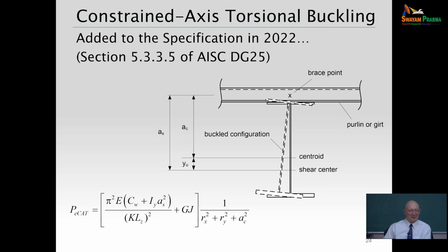But they don't go to the top flange. I've seen these details. They just go from the bottom web-flange junction, and they go diagonally outwards. And so they're not really bracing the compression flange over there.